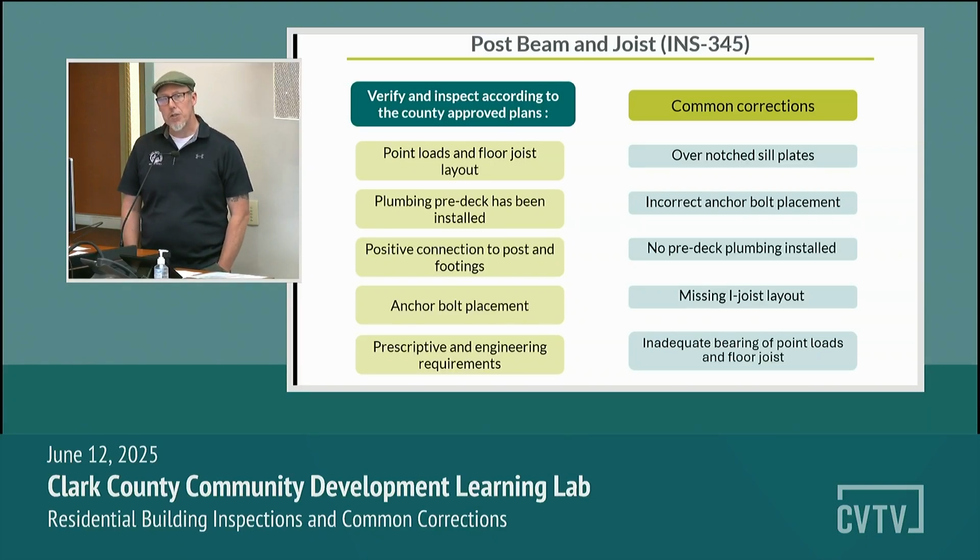The floor joists have to be supported typically with a hanger or in what's called a beam pocket, where the concrete installers will have a little pocket put into the stem walls of your foundation, and the floor joists will rest in there. Those require 3 inches of bearing, and sometimes the concrete will break or the floor joist might not be long enough, and they won't have the bearing on that.